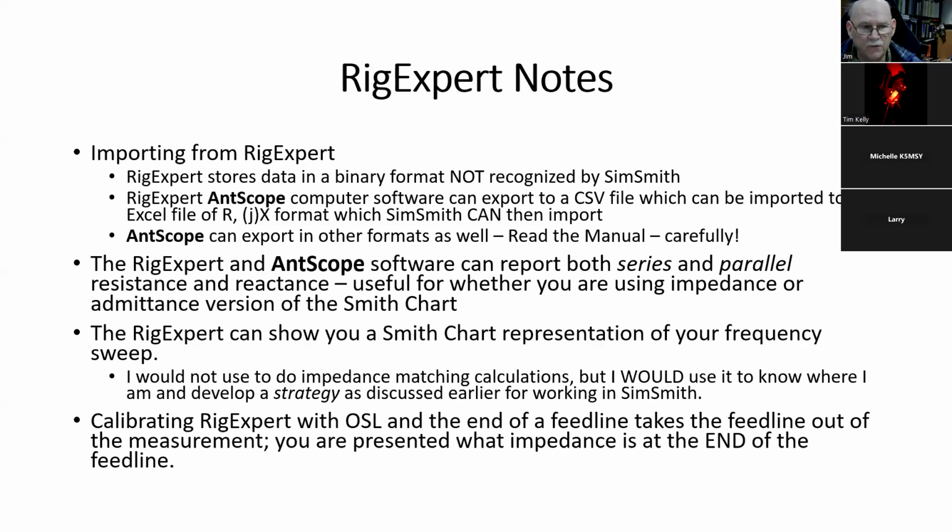But if you prowl around, you can find them cheap. And if you can go into the Rig Expert and calibrate it with the OSL at the end of the feed line, the length of the feed line does not matter. What you see on a Rig Expert is the impedance at the end of the feed line. And the fancy guys call that the measurement plane.